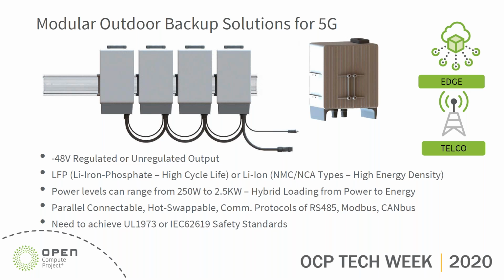We already talked about this difference between lithium iron phosphate or lithium ion. The NMC stands for nickel manganese cobalt, and NCA is nickel cobalt aluminum. So those cells are a little bit higher in energy density, and what we're seeing in that world, frankly, are some of the newer cells that have been designed for the automotive environment. Anybody can ping me for whatever level of detail, ad nauseam, that you'd like. But essentially, these are the two different chemistries that we're seeing as pretty valid for these applications.